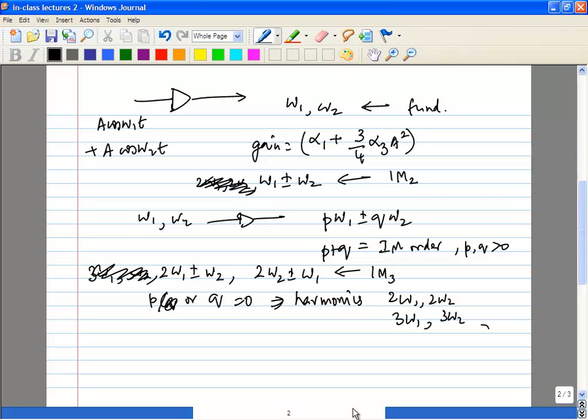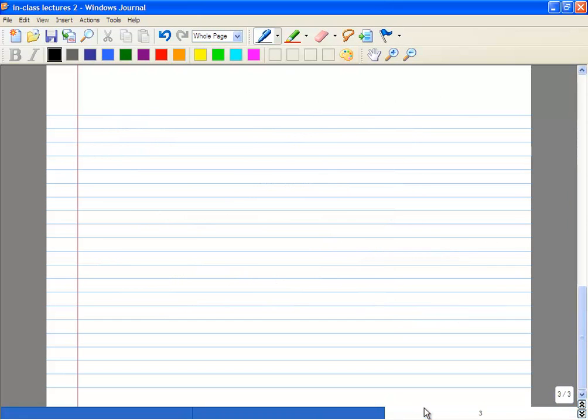Now, once you use IP3 to characterize different nonlinearities, we'll see there is a relationship, for example, between the 1 dB compression point and IIP3. So you can actually compare across systems, even if you know only the 1 dB compression point or the IIP3.